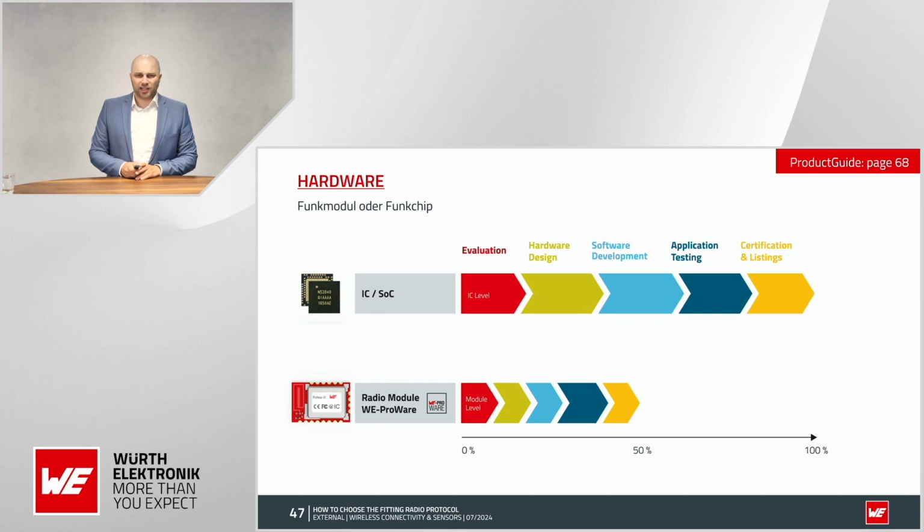Here I have a comparison between the chipset and the module, and one of the most important things is that the module is much faster in development. So you need not become a radio expert. You can use the module, start with the development, and be quite fast in bringing it into your device. Especially in the certification phase, but also in the software development and in the hardware design, you save a lot of time developing with a radio module.